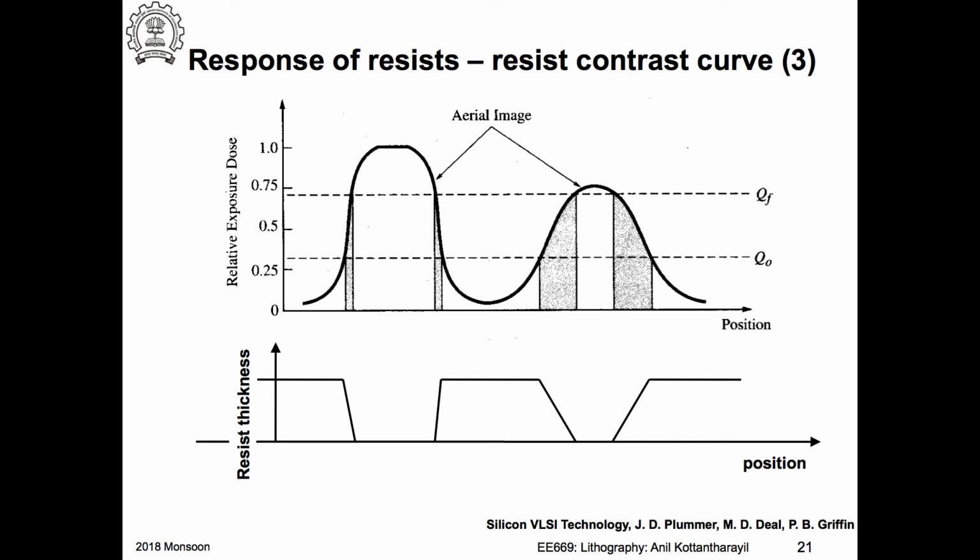And then I would actually etch the photoresist. Okay, so whatever gold is on top of the photoresist will be removed along with the photoresist. So that is what you are lifting off. Okay, so that is the name. Now if I want to do a lift-off, can I use this photoresist and this process that we are discussing? Will it actually give me a good lift-off process? Good lift-off. Why not?